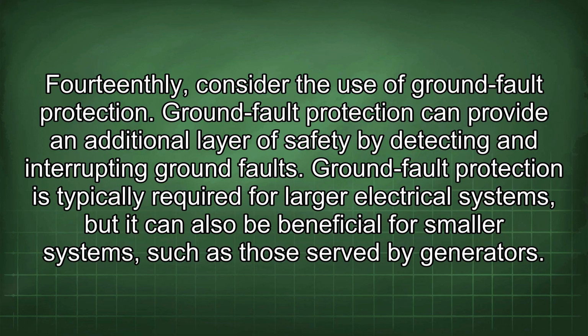14thly, consider the use of ground fault protection. Ground fault protection can provide an additional layer of safety by detecting and interrupting ground faults. Ground fault protection is typically required for larger electrical systems, but it can also be beneficial for smaller systems, such as those served by generators.